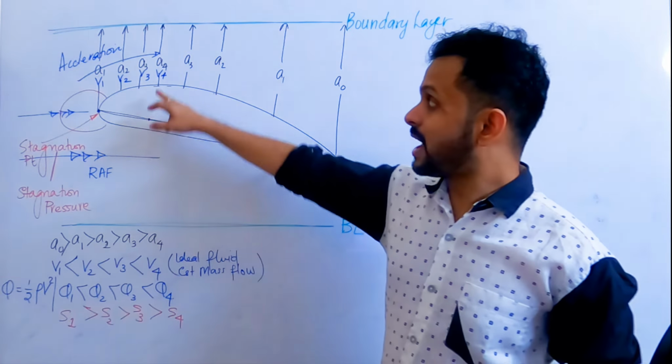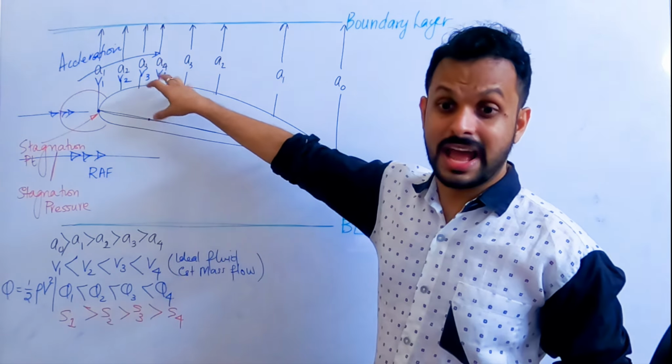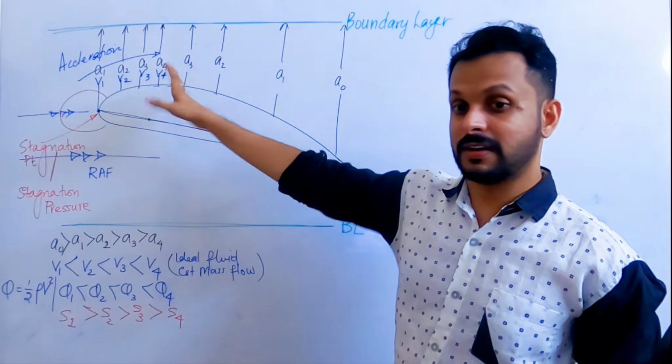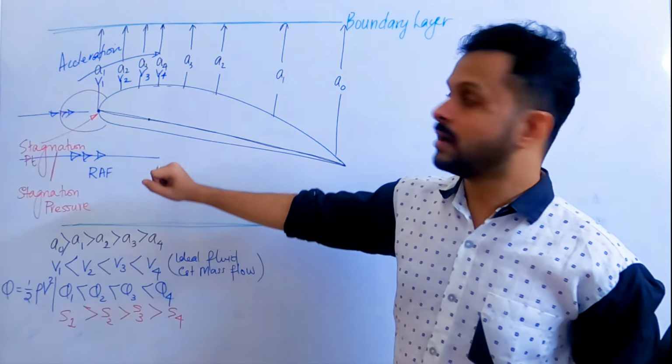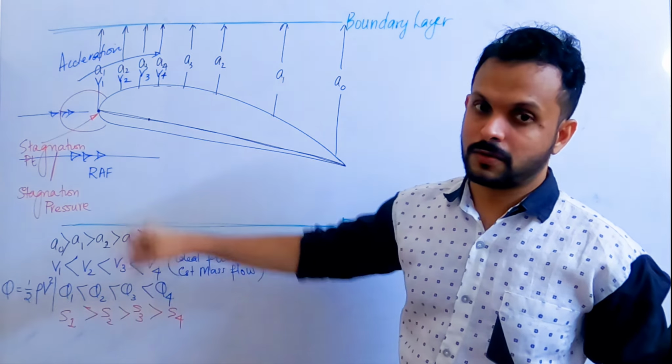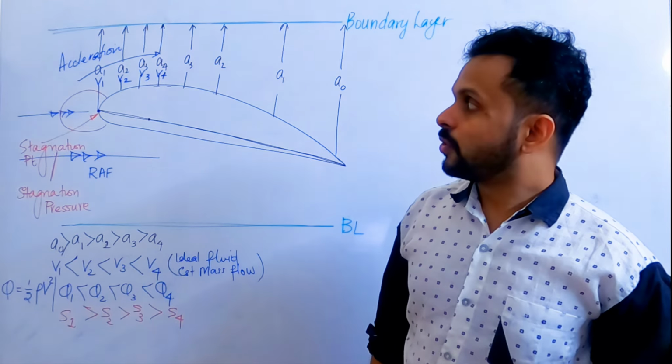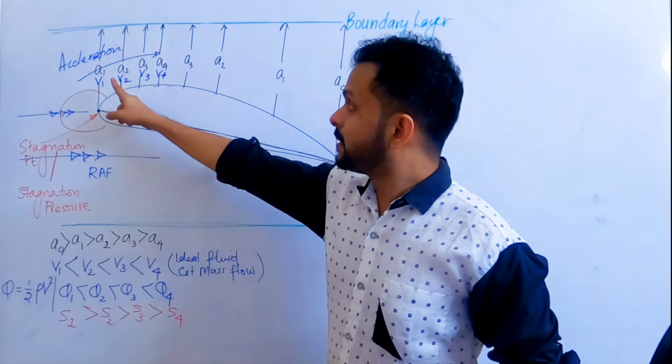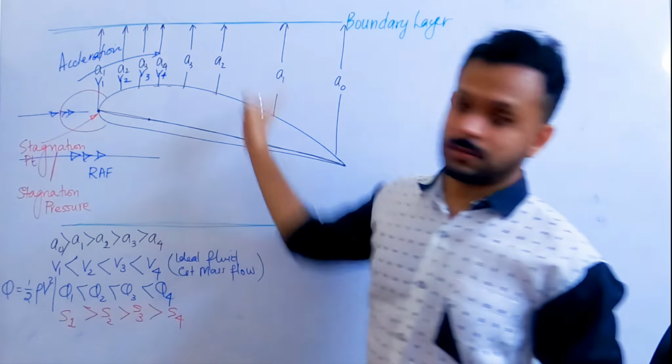So you can see, as the air reaches this particular point, at this particular configuration, we can assume that's the point of maximum thickness. The static pressure is the lowest, right? Now, so air accelerates. Now, what happens to the air after this point?